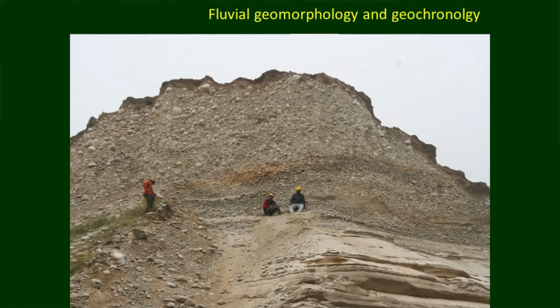Similarly, when we talk about fluvial systems, we have often seen floods like the flood of Uttarakhand in 2013. These floods generate lots of sediments, and these sediments are deposited in downstream areas. The photograph shows a river terrace, which is an example of aggradation. That means the river deposited sediments in the past up to this height, and buildings have been constructed on this river terrace. But this is an example of the river having flowed through this channel. So if we construct buildings on these river terraces, they are prone to destruction in future floods.